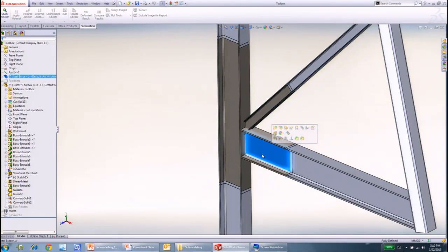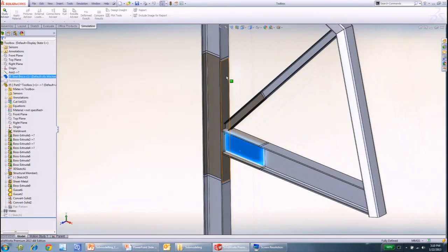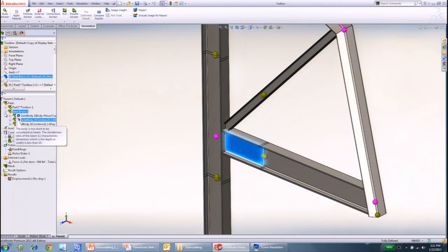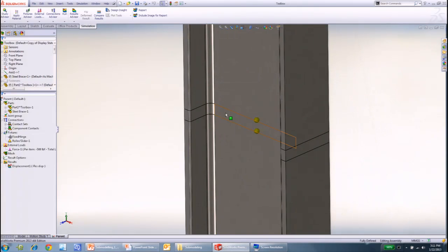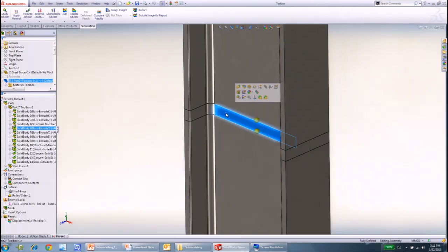So I'm going to create a much coarser model and make my judgment saying, okay, displacements are pretty close to what it is, and then apply my new joints to see if the joint will hold those displacements. So I have this. The trick here is because we cannot cut a beam and beam between the parent and submodel, I introduce an incompatibility here.